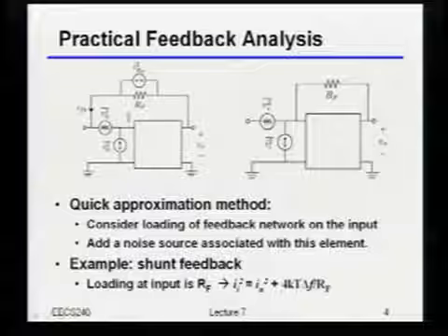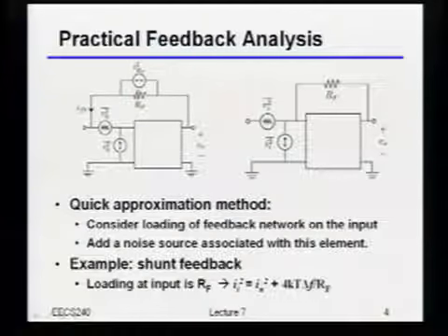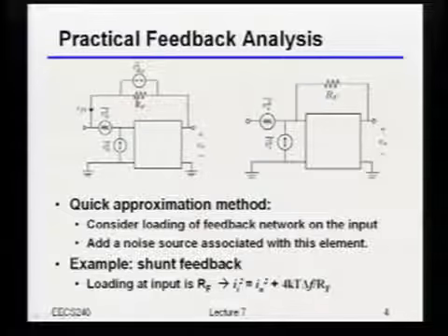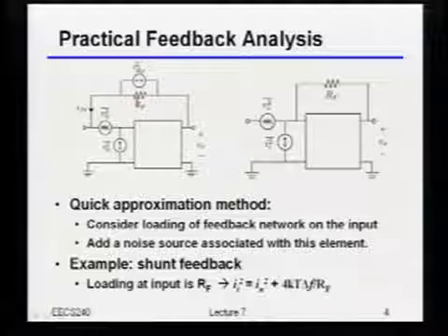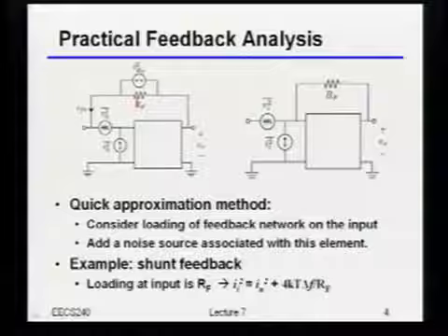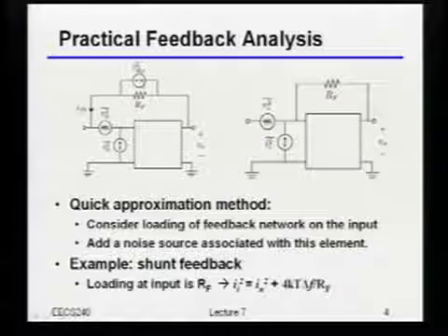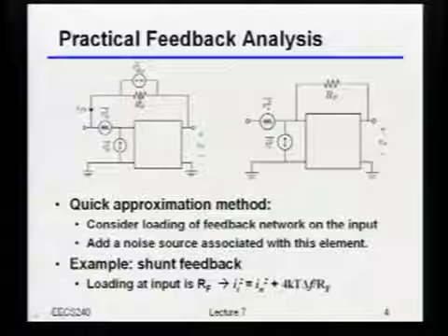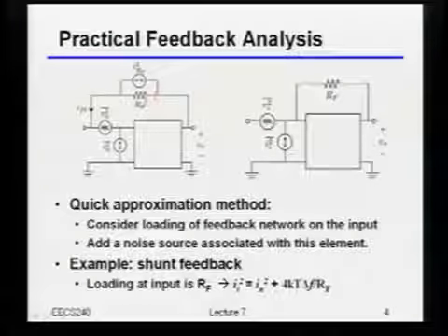By the way, I'm really interested in just what's the extra noise coming in from that RF over there. Anytime I have a noise calculation, I can do one of two things. I can either model the noise as being a current source in parallel with that RF, or a voltage source in series with that RF.